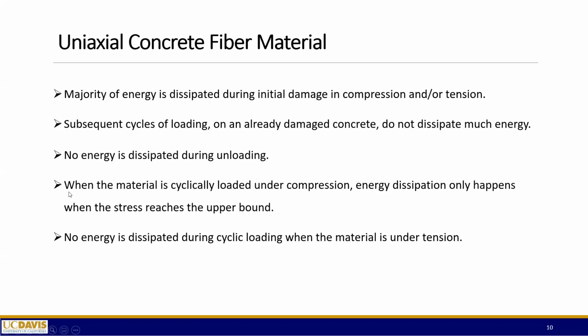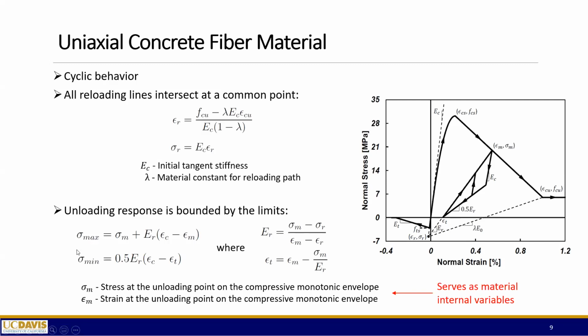Then the fourth one: when the material is cyclically loaded under compression, energy dissipation only happens when the stress reaches the upper bound. Remember, I mentioned that the unloading and reloading response of this material is bounded by those two limits. So here we assume that energy dissipation only happens when you hit this upper bound.